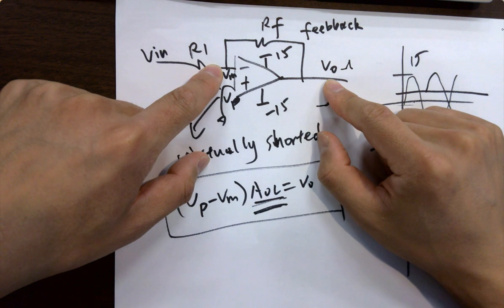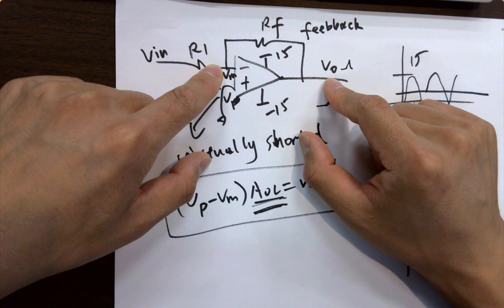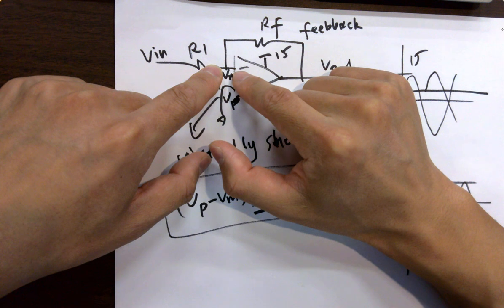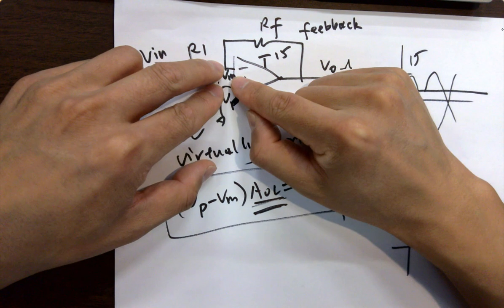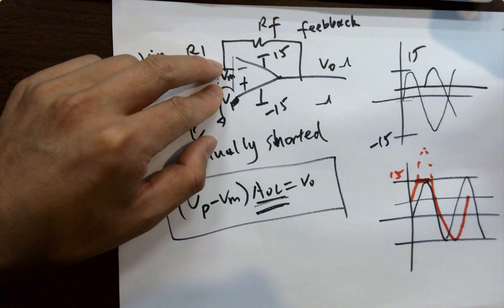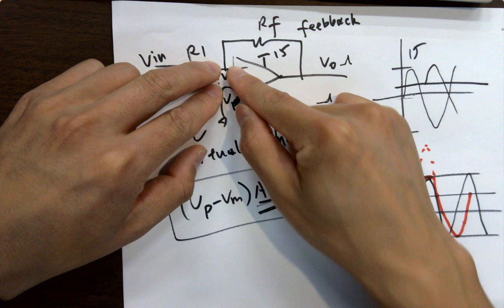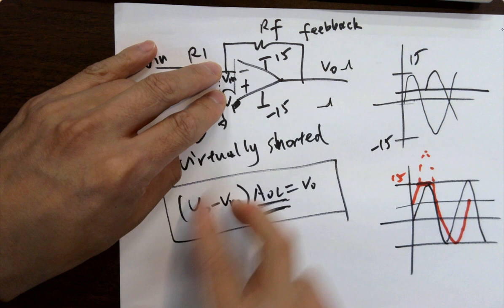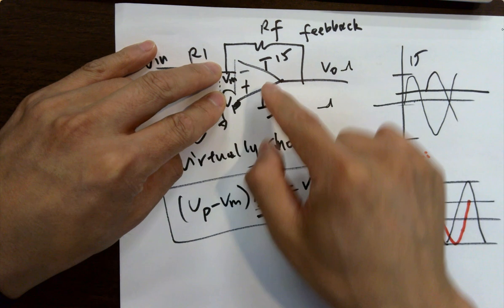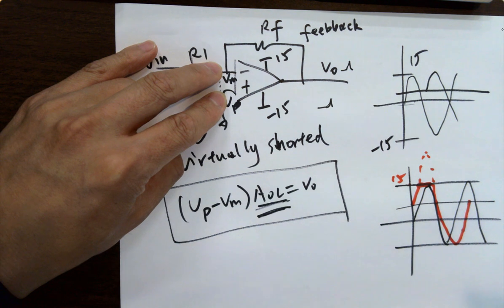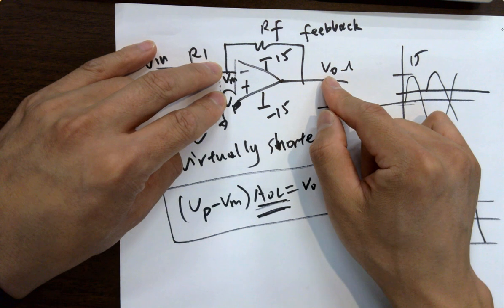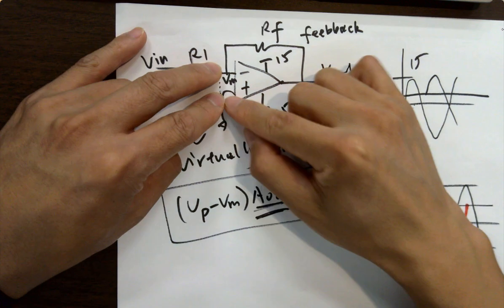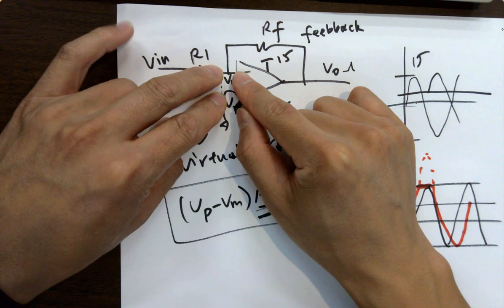Because it was not adding to it, you can think about this using superposition. So this positive voltage will contribute to this voltage and add to it. You know what I mean? Let's start from zero, from nothing. They are equal at the very beginning. If they were equal, this is 0, because of how this is designed. This minus this is 0, times whatever is still 0, VO is 0. But you do have VM to be something. It's not 0. The subtraction is 0, but VM is not 0. So it's VM over there.